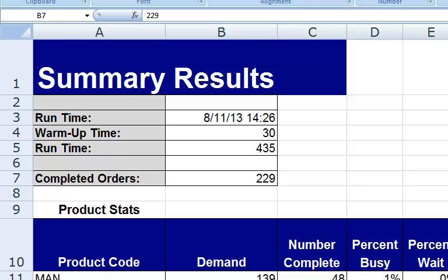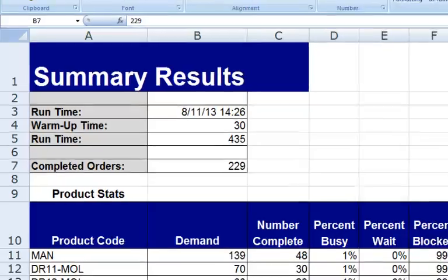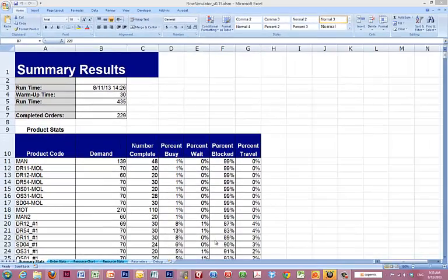And in this video what we want to do is run through various scenarios of improvement. This particular line, I happen to know, was designed for 456 units per day, or per shift in this case, one shift. And you can see here on the screen, completed orders, we're only getting 229. So what I want to do in this video is walk through the kind of analysis process we might do to improve the performance of this design, step by step, and resolve bottlenecks and get closer to that desired volume of 456 units per shift.